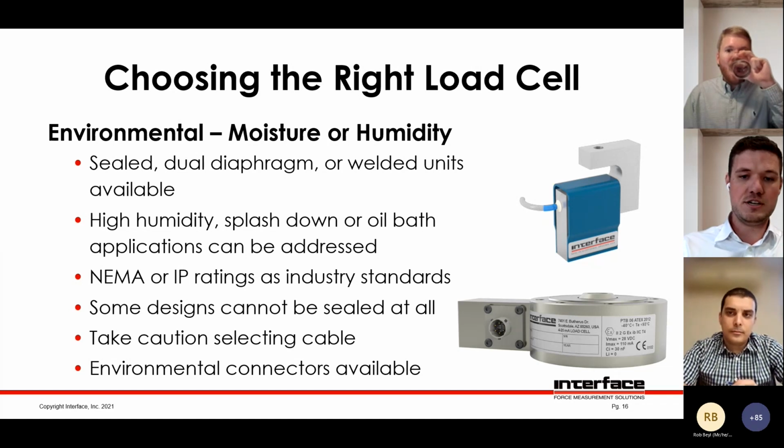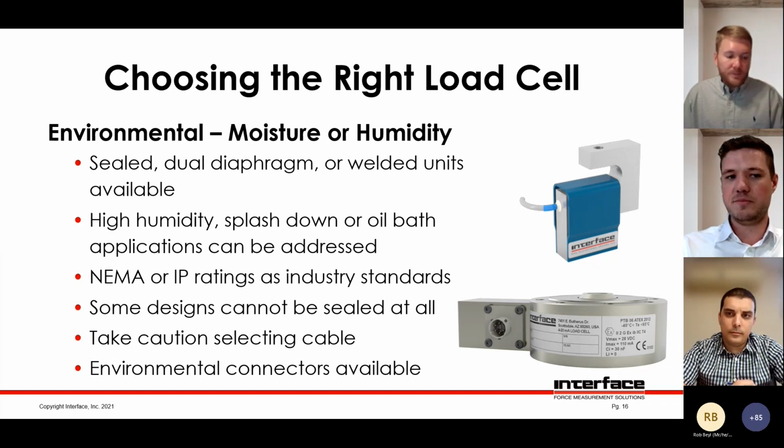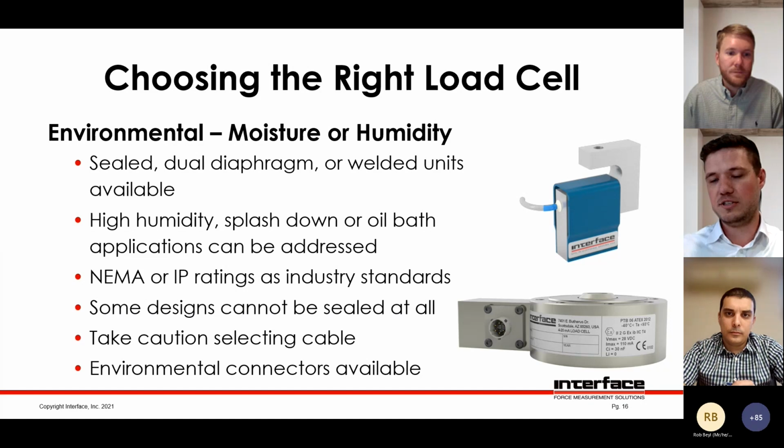And it's worth mentioning as well that some form factors, some types of load cells cannot be sealed at all just due to their nature. And also, depending on the environment, you need to take a look at the cable that you're selecting. The sheath of the cable needs to be resistant to fluids or temperatures that it might be exposed to.